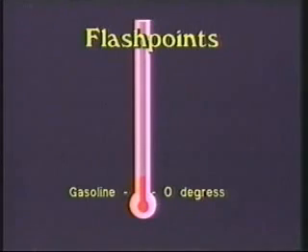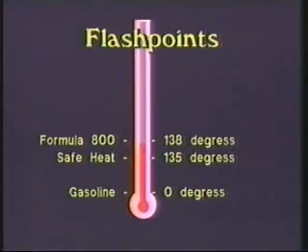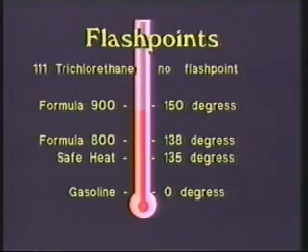Below its flash point, a solvent is considered non-flammable. Above this temperature, the solution will burn if ignited. It's best to work with a cleaning solvent having a flash point of at least 135 degrees. When purchasing cleaning products, request a material safety data sheet. This sheet will identify the product ingredients and the flash point. It will also alert you to any potential product hazards.